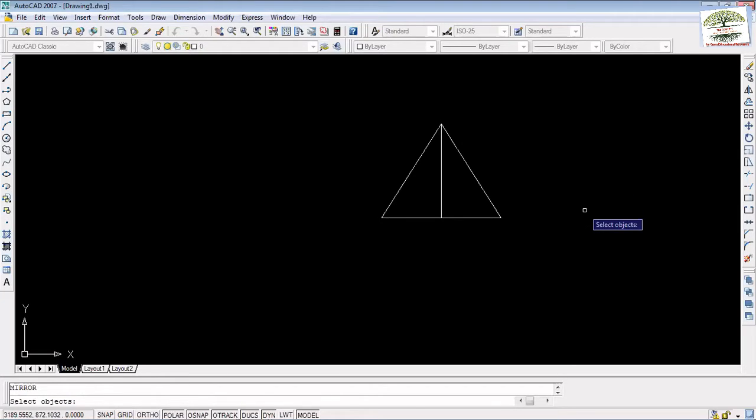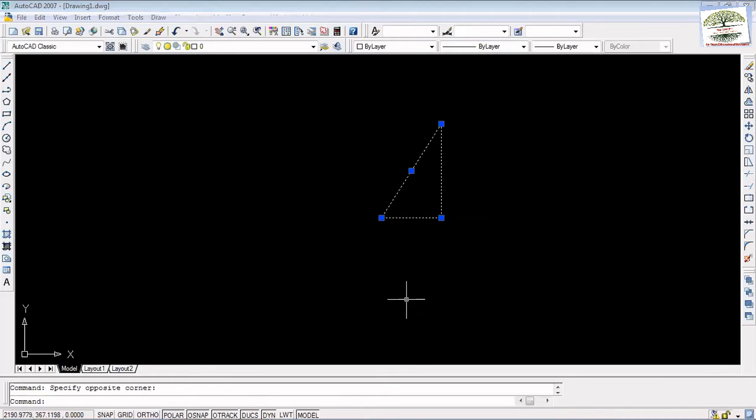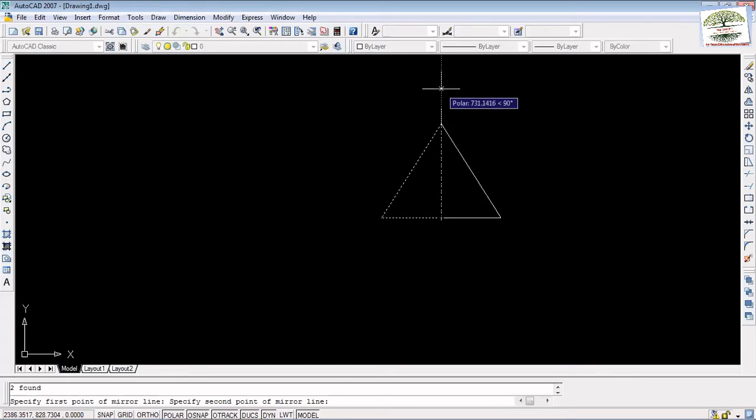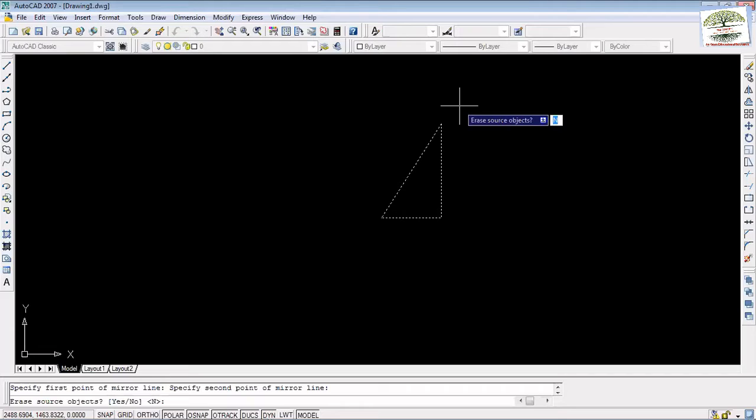So fully, you have to complete the selection of the object that you would like to mirror. Then write MIRROR in the white part. You will see that mirror is there. Space bar or enter, we can go for anything. Select it, it vanishes, don't worry, double enter, 1 2, done.